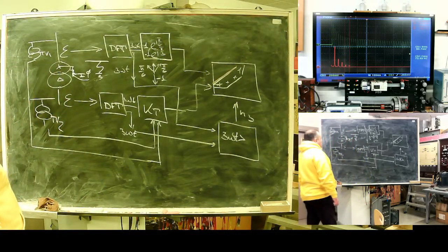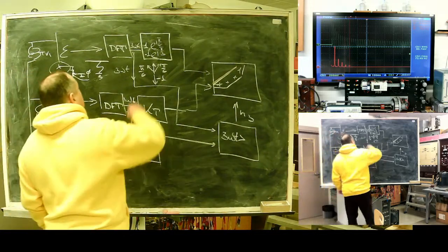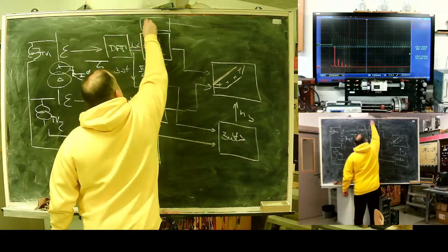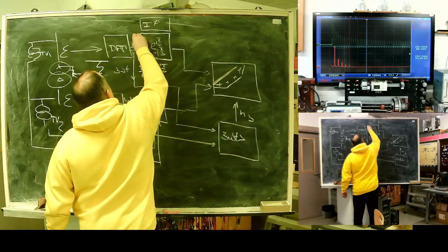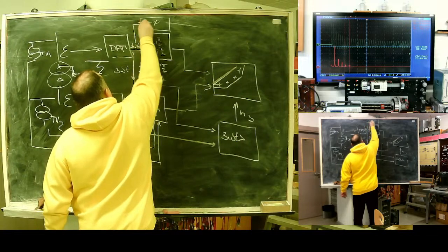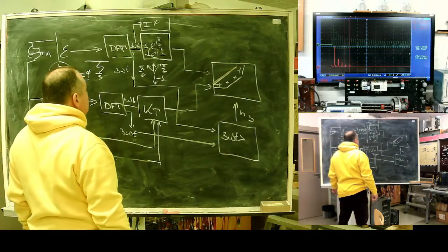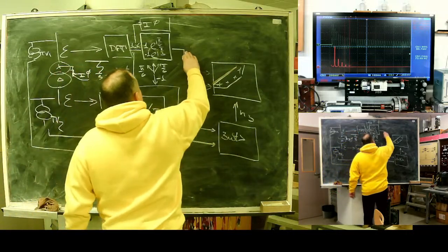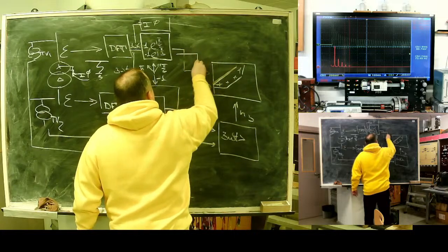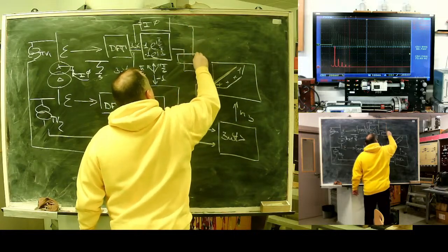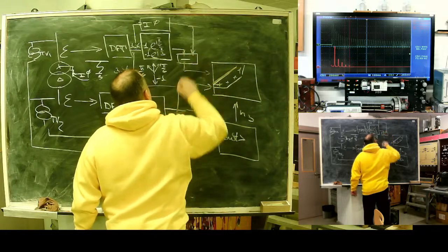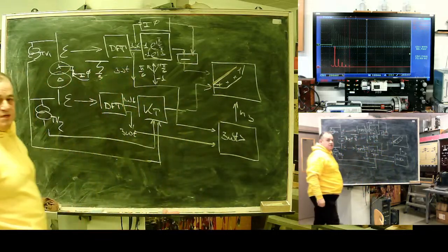To prevent this, we need a correction. Zero sequence current should be eliminated from the differential.